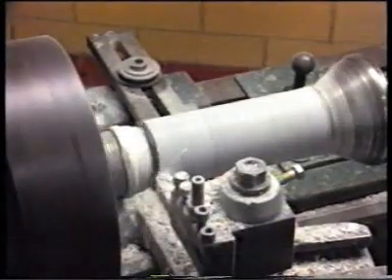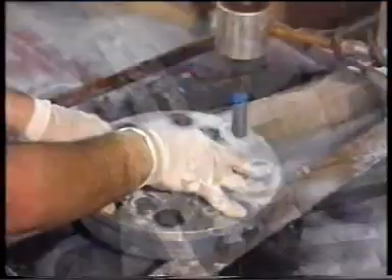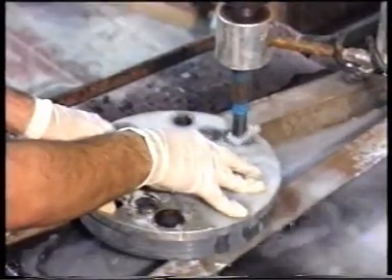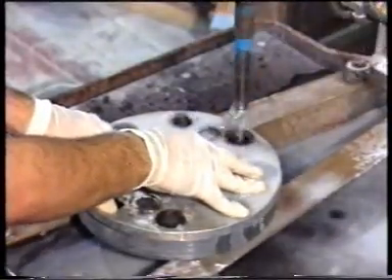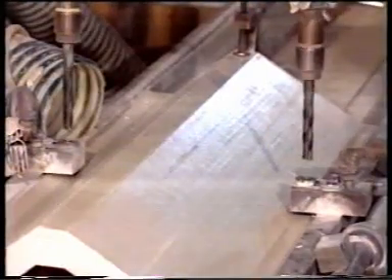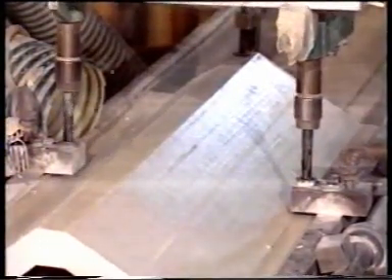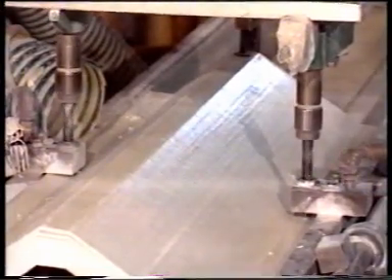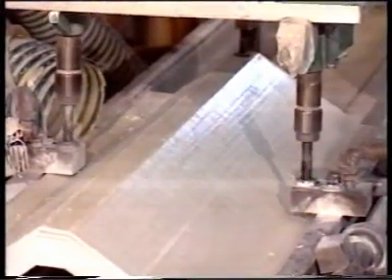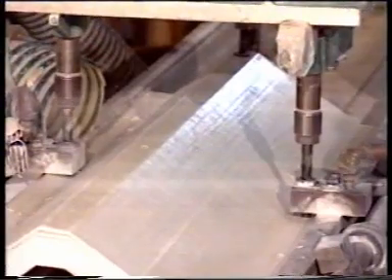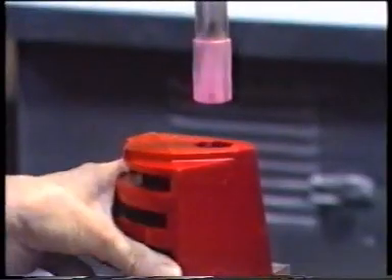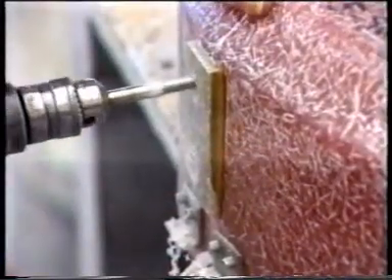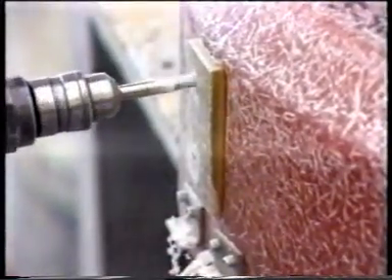In machining operations such as turning and drilling, speed should be somewhat greater and feeds somewhat less than for metals. For drilling, large positive rake angles are recommended to reduce the penetrating force and thus heat buildup. Drill flutes should be wide and polished to ease chip removal. Secondary operations, such as reaming and threading, can also be performed on composite parts.